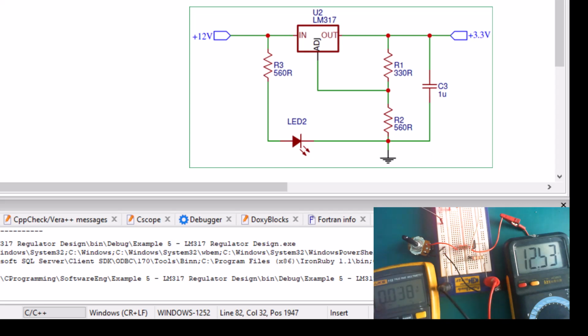Now as I go up all the way, I'm getting about 17 volt. It seems like my output voltage is not increasing anymore. It has stopped at 17. Now I've reached the end of my potentiometer. Now notice this, as I start to come back, the value on my output does not change that much, all the way until I'm almost right in the middle of the potentiometer. Then that's where my voltage actually starts to change.